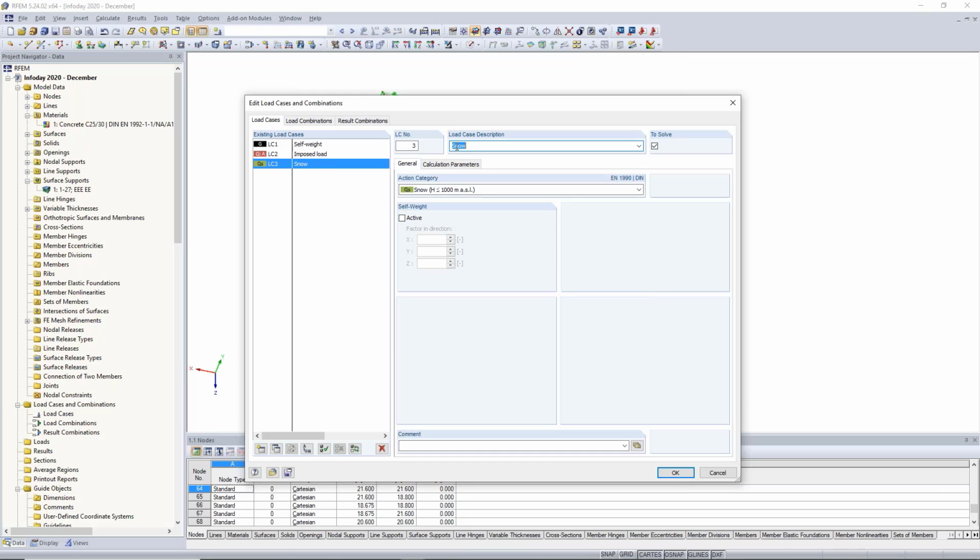You see, if I select this pre-installed load case description, the program automatically knows also the action category, and this setting comes in my case from the Eurocode, which was predefined in my base data from this file. I will tell you some words about this in just some seconds. The next step would be the wind, and I can create it also in all directions.